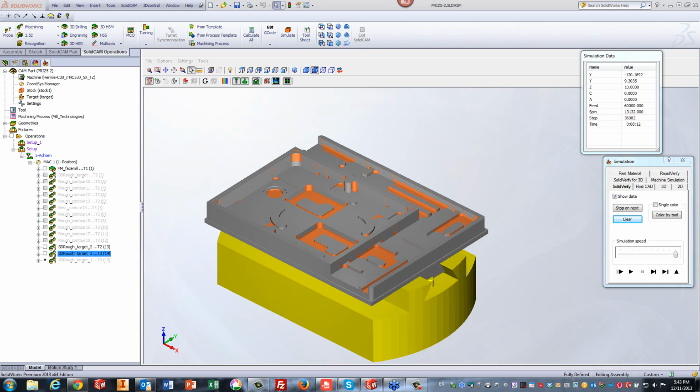What we'll also have in the prismatic part for iMachining in 2014 is the option of controlling the amount of steps you have on the bottom there on the floor itself. But you can also do that with the way you have it now, just by making a smaller scallop for your step-ups inside your iMachining 3D, and you'll get your small steps on those radiuses on the floor itself. Okay, any more questions?